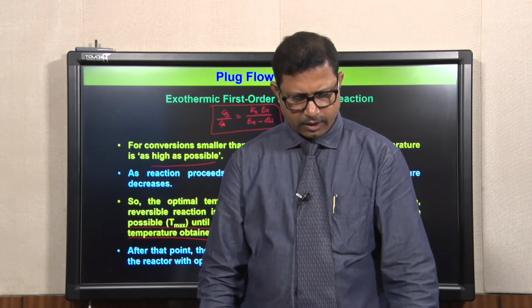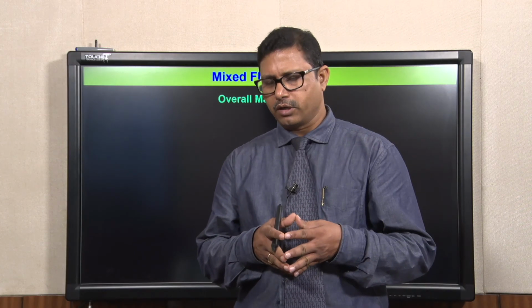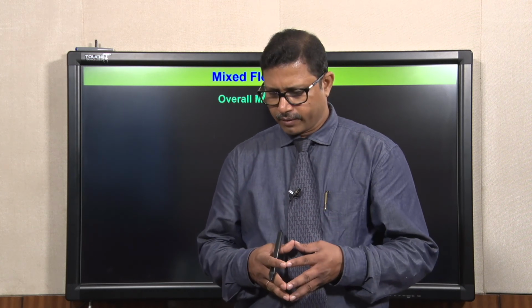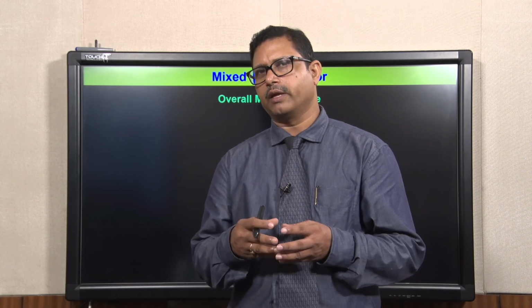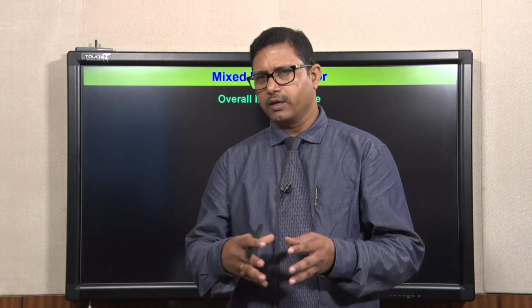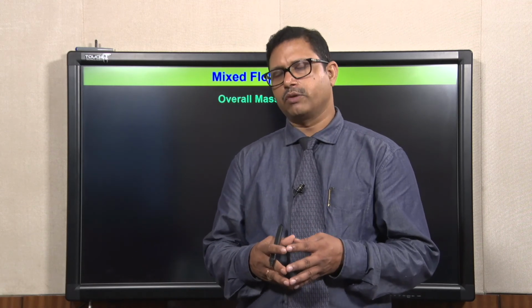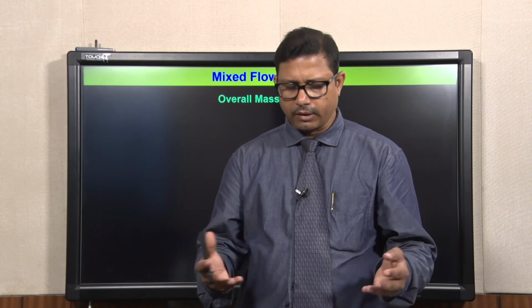So, now let us consider the ideal mixed flow reactor overall mass balance. As we have discussed earlier, for the mixed flow reactor, because of the homogeneous mixing of the contents of the reactor, the concentration is uniform everywhere inside the reactor. So, there is no spatial distribution of the concentration inside the reactor. So, the steady state mass balance equation for CSTR is an algebraic equation.